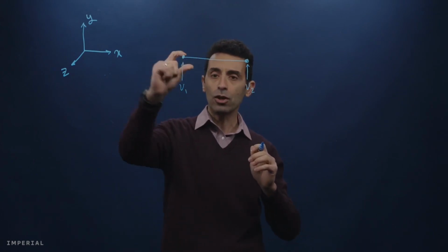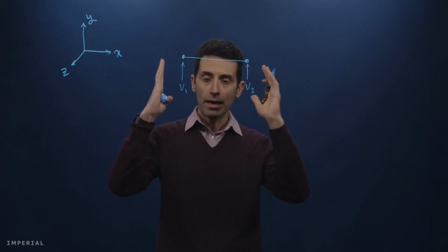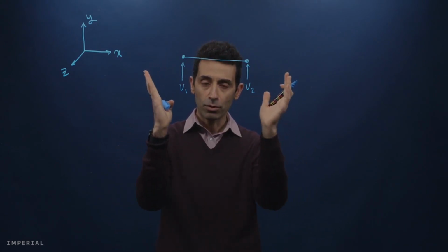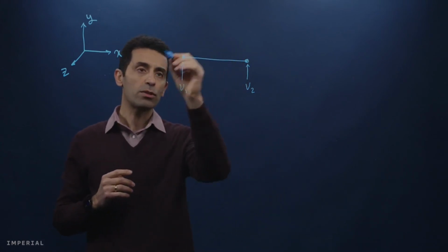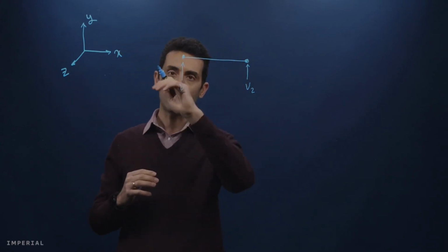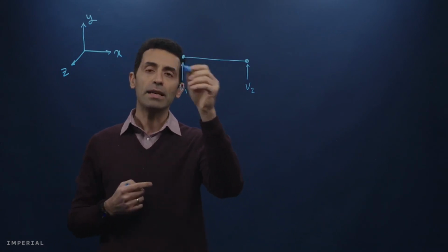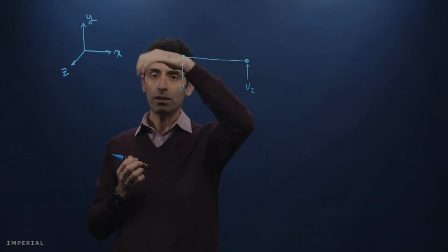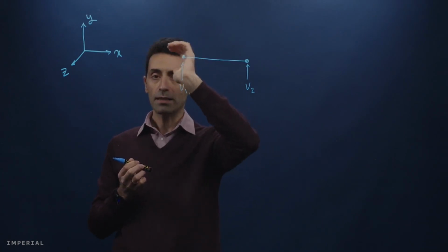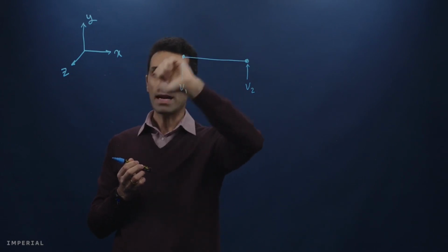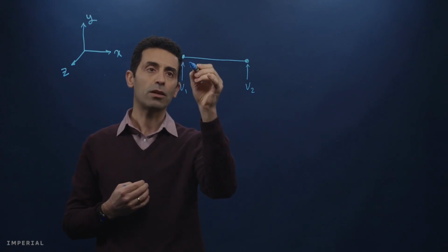And then each node can also rotate, because this is a beam, every cross section can rotate as bending is happening. And we call this rotation about the Z axis, theta Z. And then the positive convention, the right hand rule, is that when you rotate these 4 fingers around the Z axis, your thumb should be pointing towards the positive direction of the Z axis.